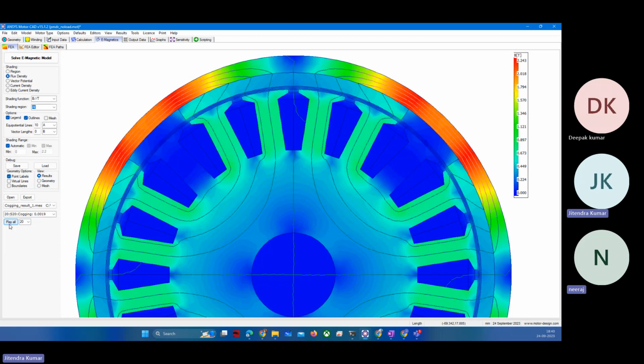In a synchronous machine, our field winding rotates, right? To rotate the armature winding field or stator field, we provide a three-phase balanced supply, 120 degrees phase displaced in space. That creates a rotating magnetic field, which will rotate at synchronous speed by the nature of the supply we provide to the stator.